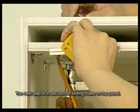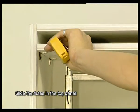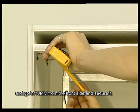The next step is to secure the sliding flutes on the top panel. Slide the flutes in the top panel and go in 70 mm from the front side and secure it.